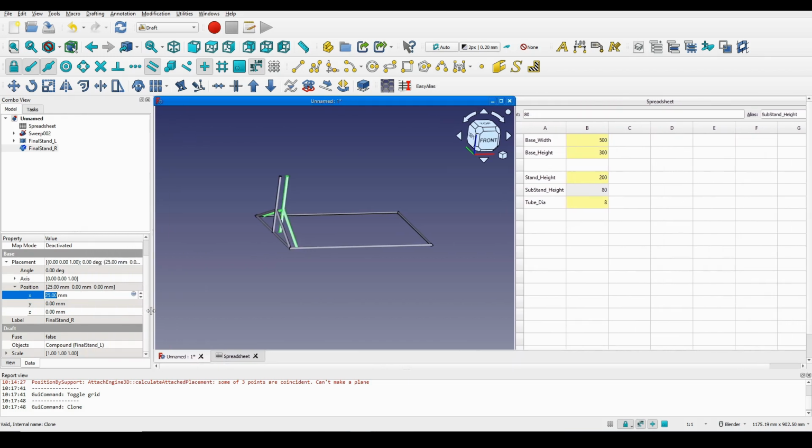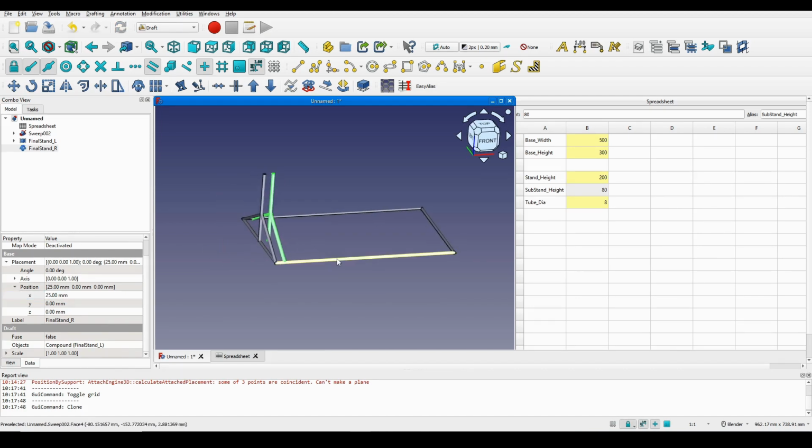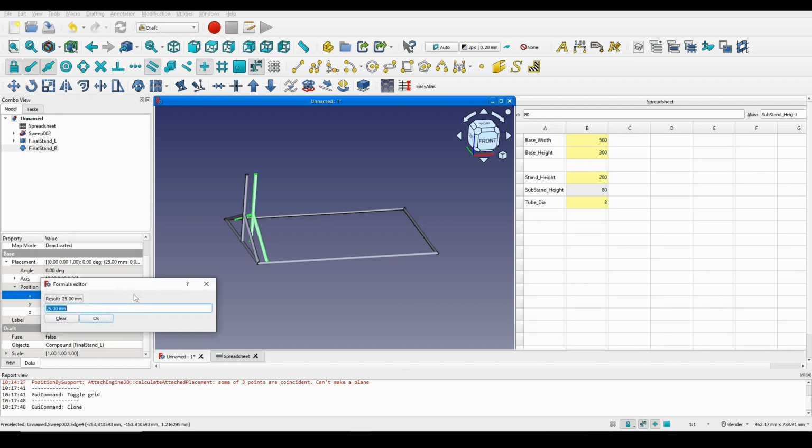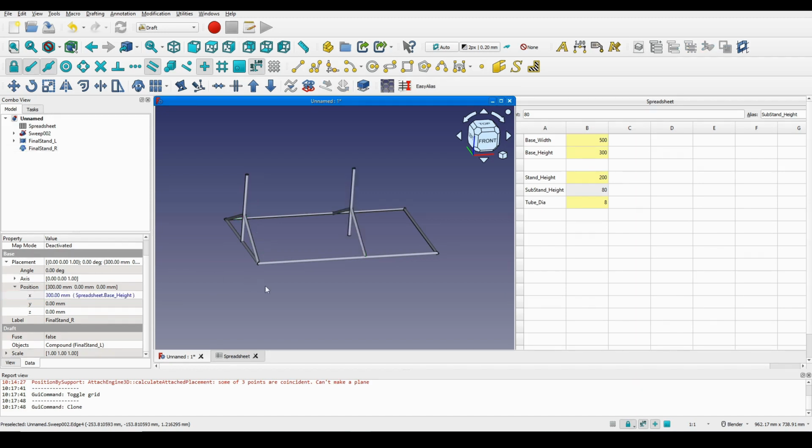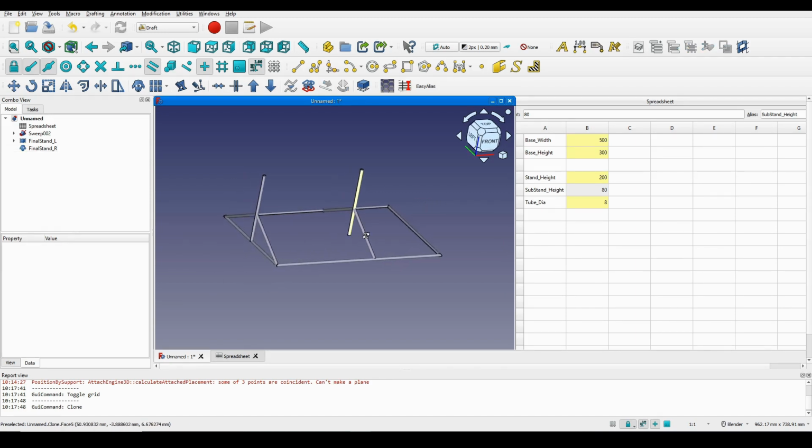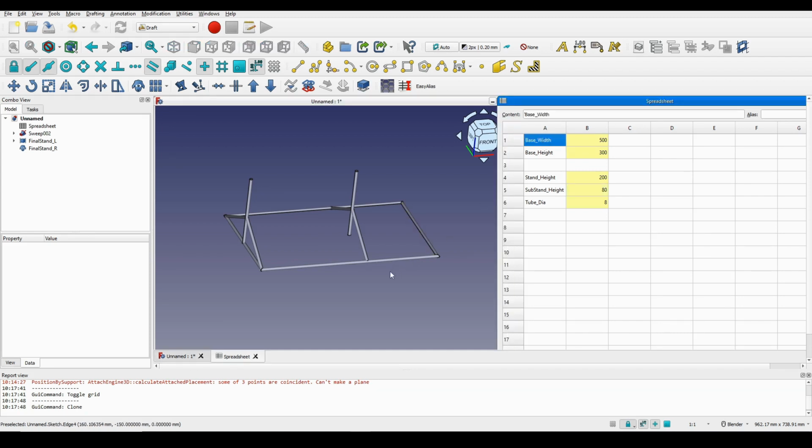So I want to constrain this one with the same number as the base underscore height. I think let's change it. I click on the FS, and I constrain it, Spreadsheet, this one, put it down, and base underscore width or height, I think 300 maybe, but base underscore width is the correct one.